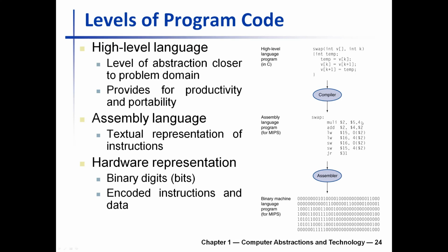what you have in the machine code is a composition of this instruction, right? Some pattern of ones and zeros somewhere here will say this instruction is multiply immediate. Then the rest of the regions of ones and zeros will define the destination, the first operand and the second operand. You can figure that out looking at the MIPS instruction set. So that is how your program is translated into machine language.